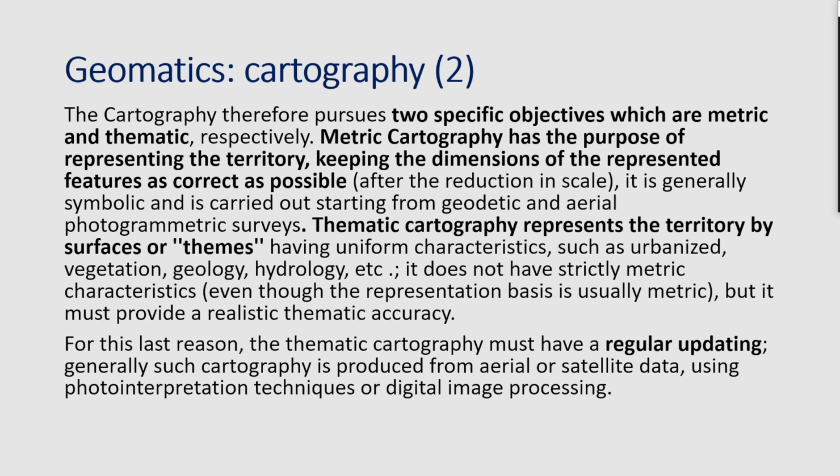Thematic cartography represents the territory by surfaces or themes having uniform characteristics, such as urbanized areas, vegetation, geology, hydrology, etc. It does not have strictly metric characteristics, even though the representation basis is usually metric, but it must provide a realistic thematic accuracy. For this last reason, thematic cartography must have a regular updating. Generally, such cartography is produced from aerial or satellite data, using photo interpretation techniques or digital image processing.